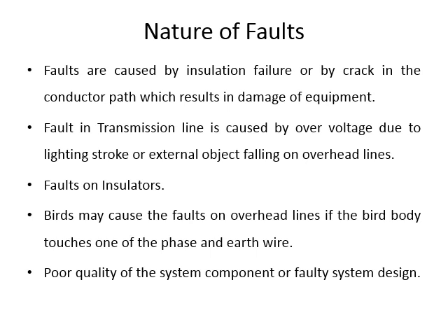So the joint failure of the cable or the overhead lines is also a cause of failure of the connecting path. The opening of one or two of the three phases makes the system unbalanced. Therefore, unbalancing of the lines is not allowed in the operation of a power system.